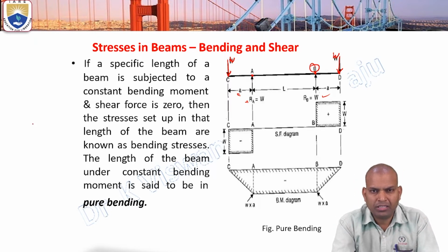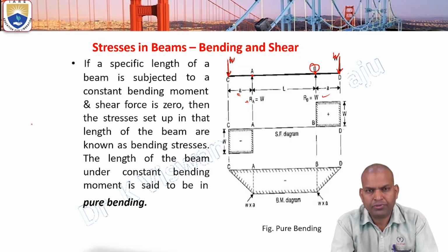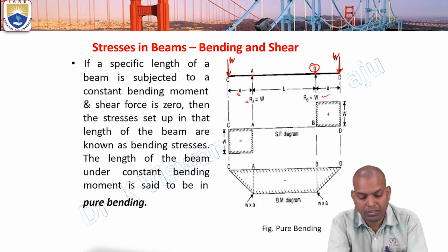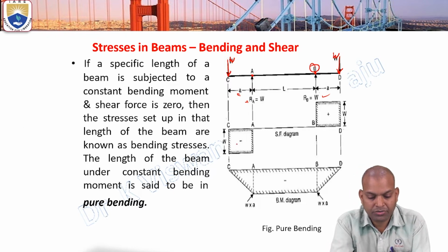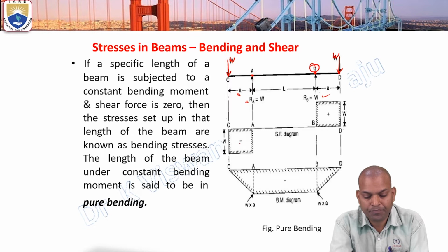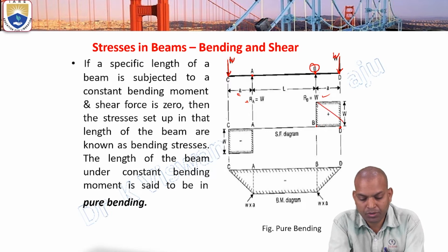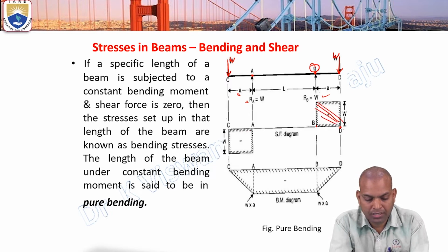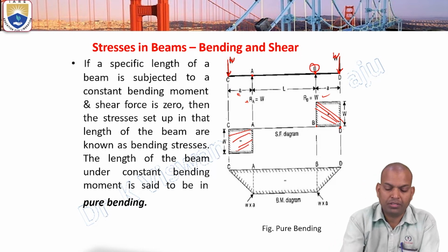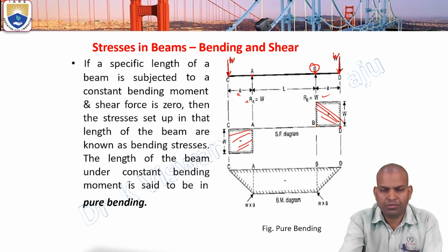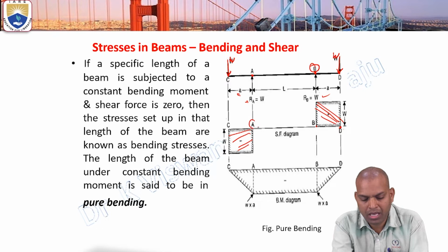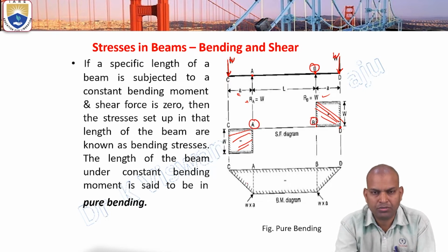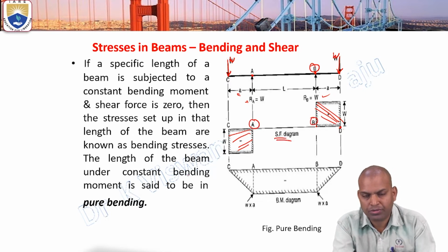After calculating the vertical reactions and drawing the shear force diagram, the shear force is observed as negative on the left between C and A, and positive between B and D. But the shear force is completely 0 between points A and B, with no effect of shear force.